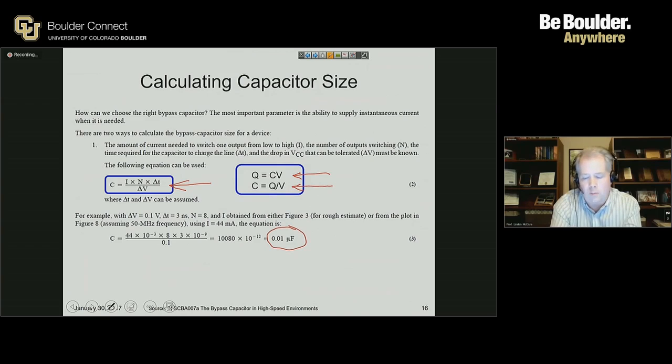You don't want to just put in a circuit element that's exactly equal to this calculation. You've lost any margin that you might have wanted. So this gives you a boundary, and then you make the choice. Okay, it calculated 0.01. I feel comfortable I could put in a 0.1 microfarad capacitor, and that would be plenty to accommodate this load.